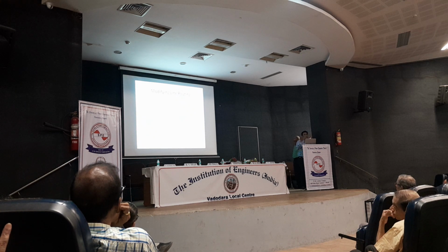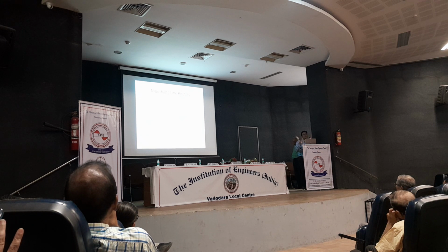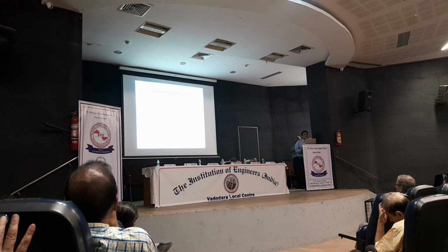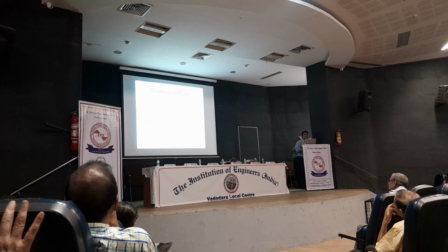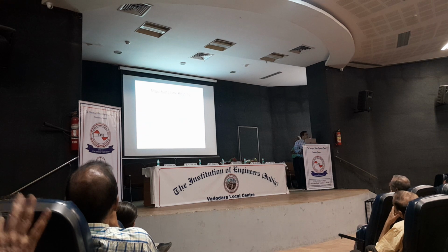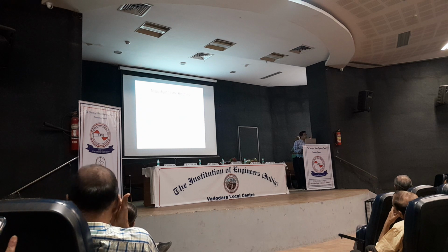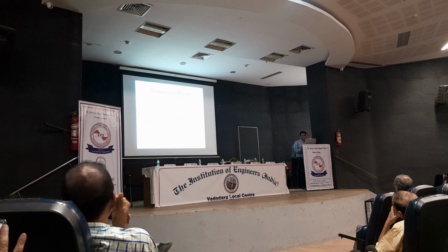So if you want to remove the line, or the generator, or the load from the network, you can just click on these square boxes. It will be out of the system, and you can simulate your contingency cases. If you want to do various contingency analyses, you just have to click on these square boxes so that the component will be out of the network.